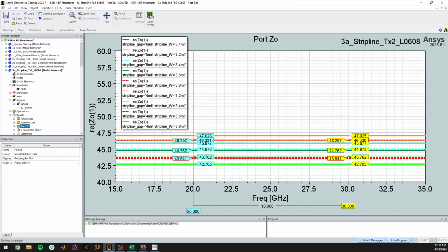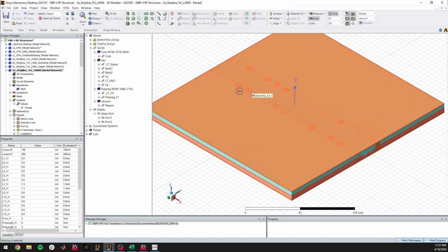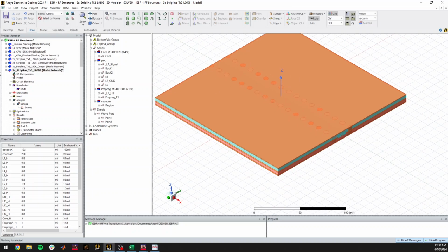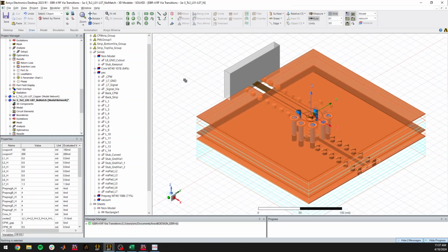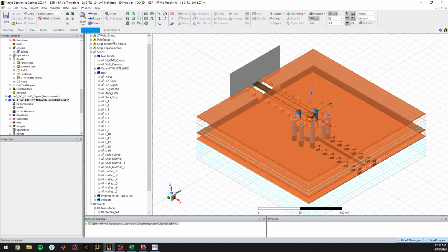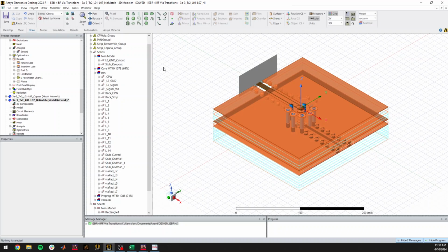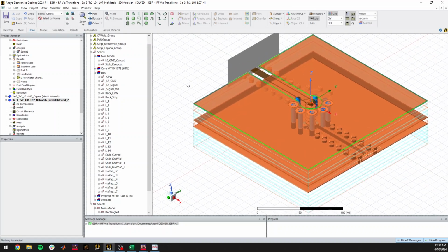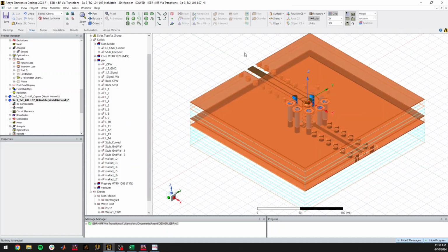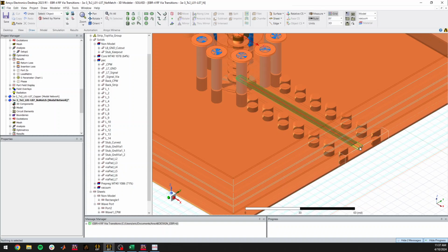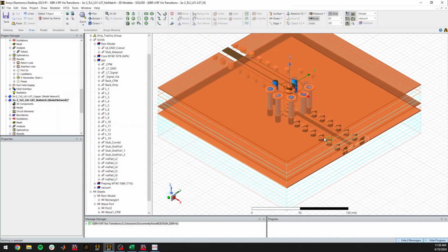So, from there, we have the two building blocks here. We have the stripline and we have the CPW design, and next we're looking to match those together. So this shows a very high level design that uses all the stack-up layers from before, so all 14 layers, and it combines the designed CPW dimensions with the designed stripline layer dimensions.